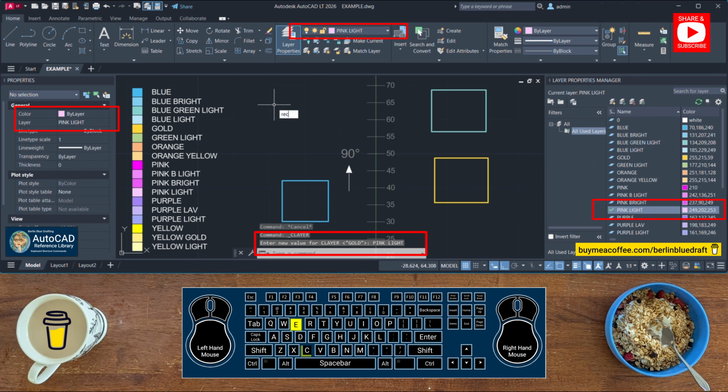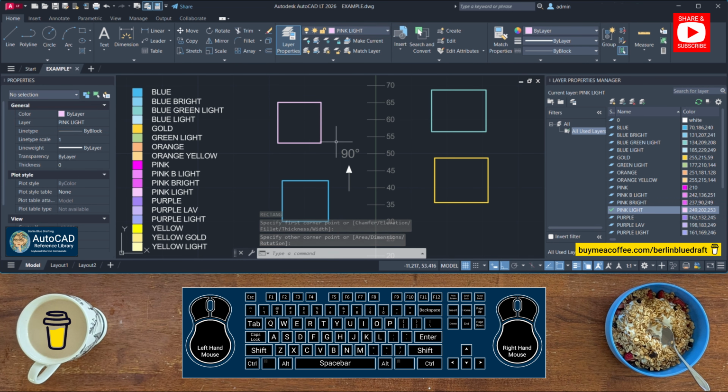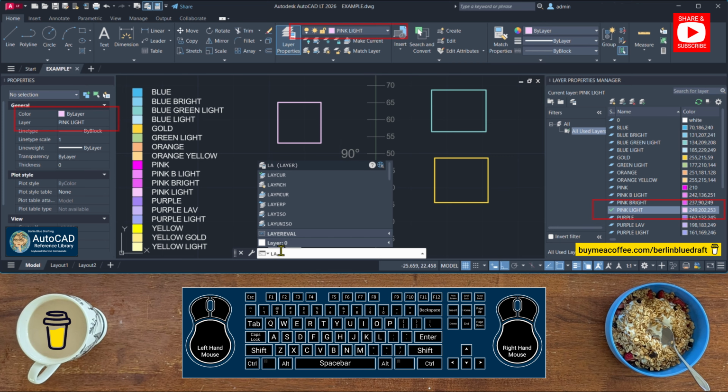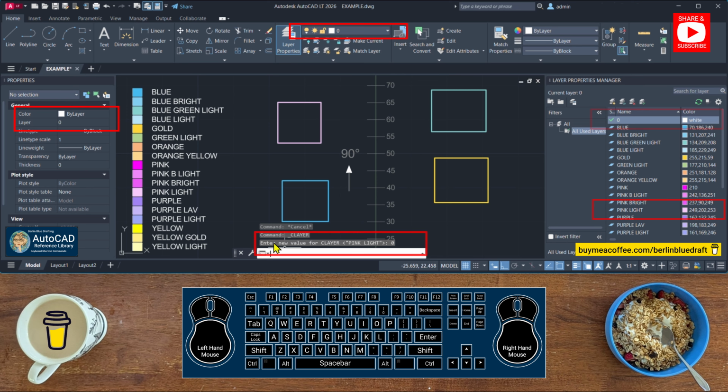As shown earlier, you can also type LA, open the autocomplete list and select a layer from the expanded list. However, if you type LA and click the word Layer 0, you have essentially selected Layer 0. Just type the layer name to bring up the options. For example, typing OR will show the orange layer. Typing BRI into the command line will display all layers containing bright.